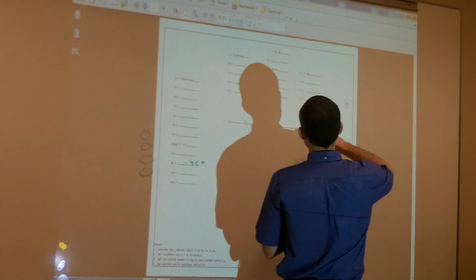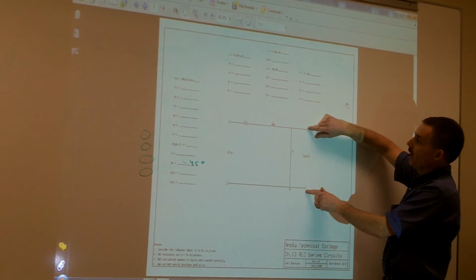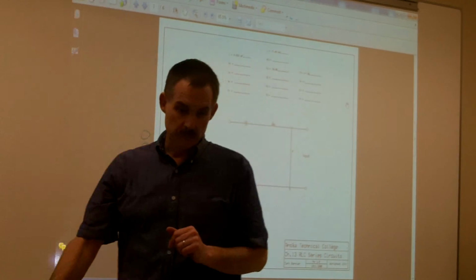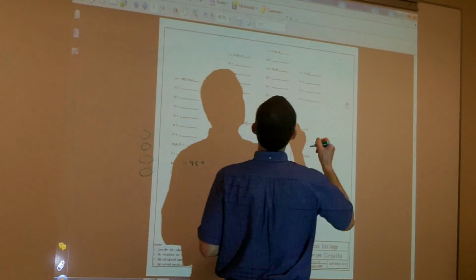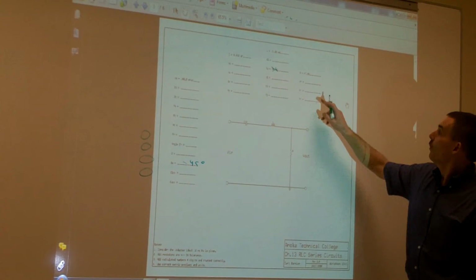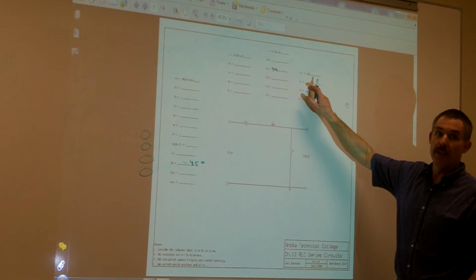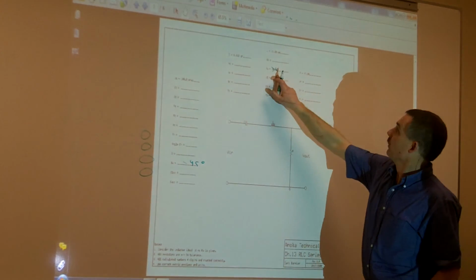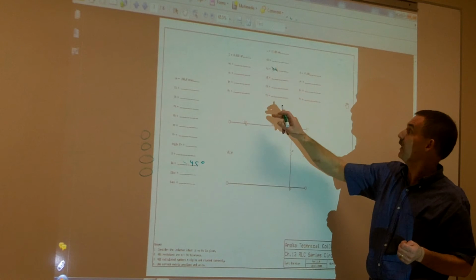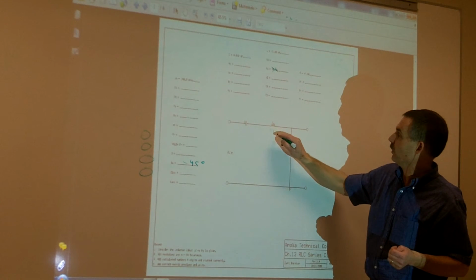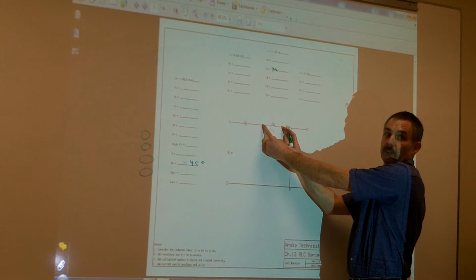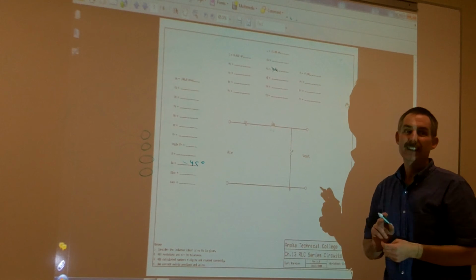That's why we're losing, because remember that my voltage across my resistor, if that was ideal and I didn't have any resistance of the windings, my voltage across my resistor on my output would be equal to my source voltage. But since I have the resistance of the windings, a portion of that voltage is going to be dropped across that winding, which is right here. So I'm going to lose about 40 millivolts across just that inductor, which is unmeasurable. If I measure it, I'm going to measure the voltage drop across the inductor, not the resistance. That's why I was wondering why your bandwidth would increase.